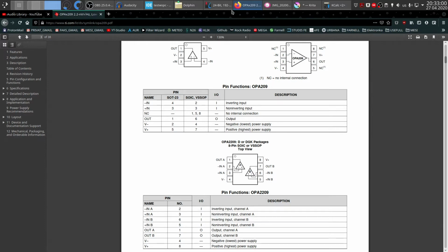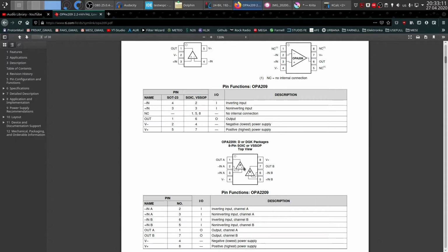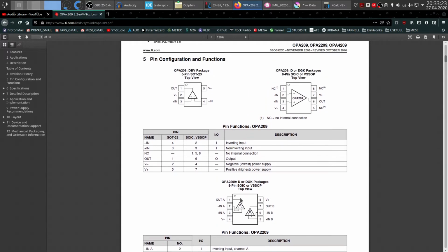So when we're talking about the IV converter, for example, which includes 2 same configurations, it would maybe be better if these 2 were integrated in the same package. But you have the trade-off of the power loss in the same package, so it will be heating up much more. Therefore you should maybe be looking for packages that have a thermal pad on the bottom, so it can dissipate that heat further. So it's up to you, there are positives and negatives in both cases.